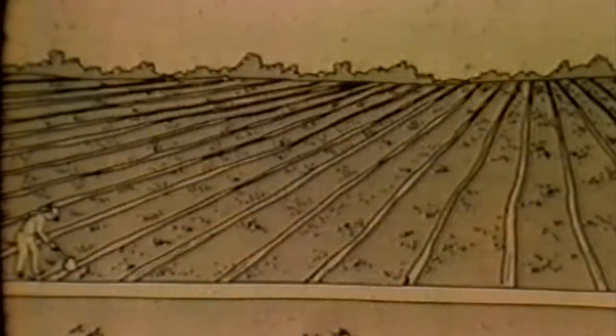The corrugation type of surface irrigation is a small graded furrow method for sown or sodded fields. When irrigating, water is turned into the small channels that are evenly spaced across the field. The water soaks into the soil and spreads laterally to irrigate the entire area. The channels are spaced so that the water wets the soil in the ridges by the time it has finished flowing in the furrows.